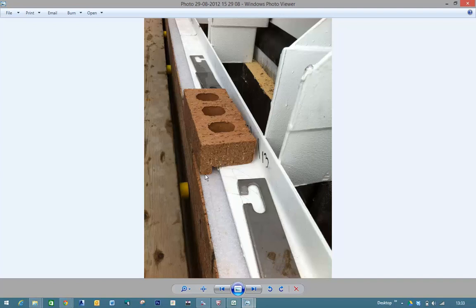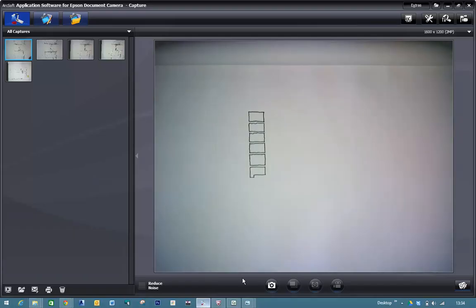And this is called a pistoled brick because it looks a little bit like a pistol. Not much, but a little bit. Okay? And so we're going to pistol that brick, because if we just sat a normal brick on it, then you're going to lift that brick up and you'd see the edge of the stainless steel through it. So we pistol the brick, we chop a little bit out of it. And a skilled brickie can do that on site, or sometimes they pre-make them in the factory for quality purposes. So let me just draw that detail.